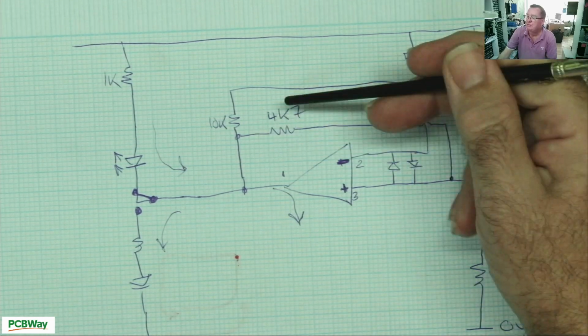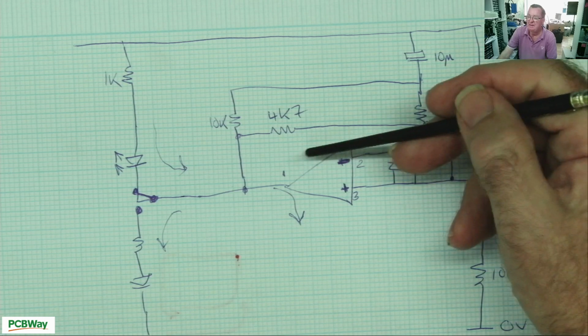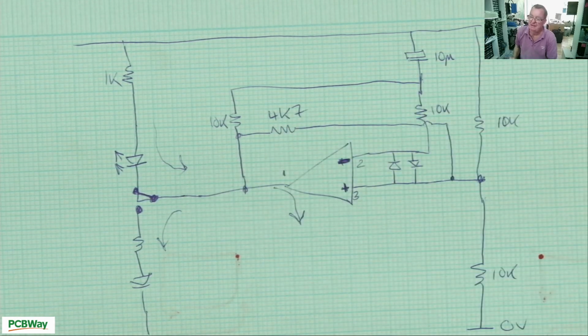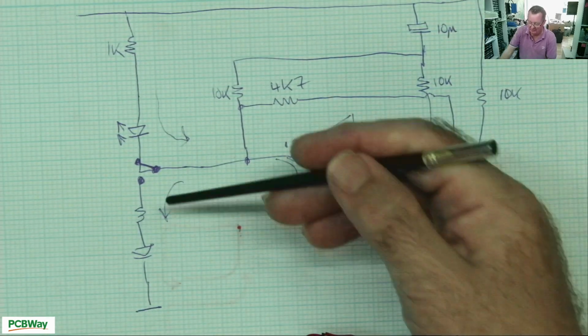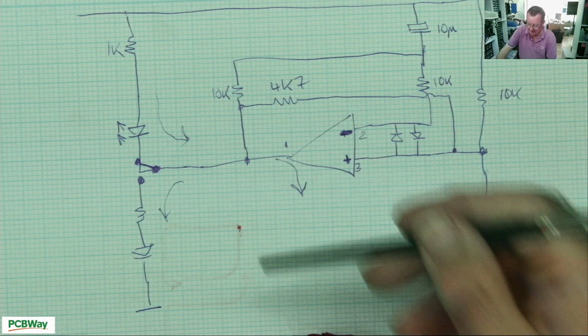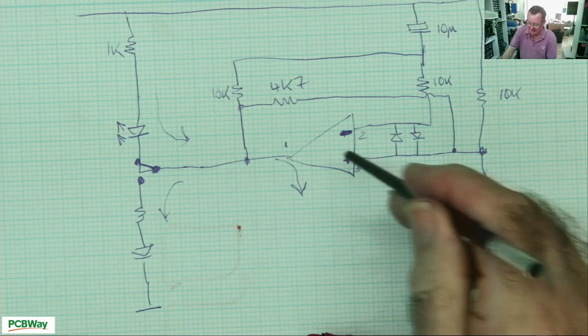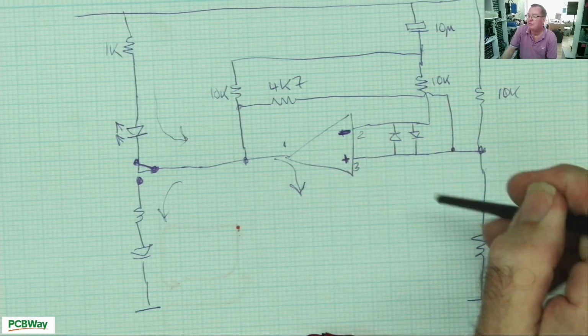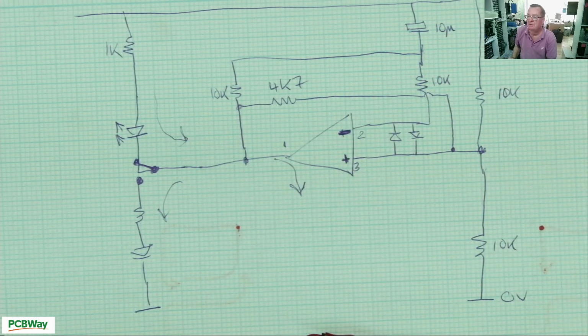And although the resistances are quite high, 15k, it's still enough to light the LED dimly, and that's why the LED is coming on when the switch is in the down position. This isn't providing current, it can't. That bit of the circuit is. Okay?